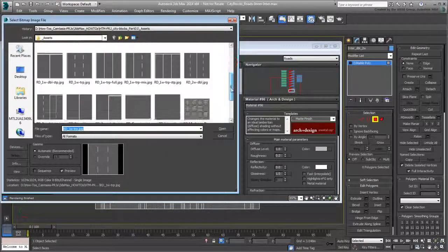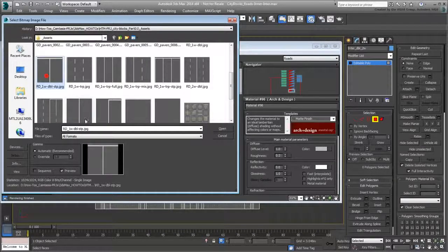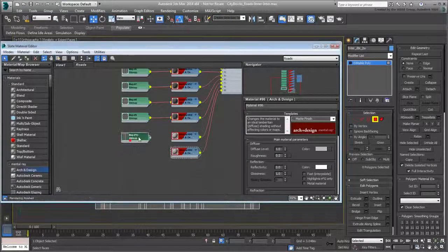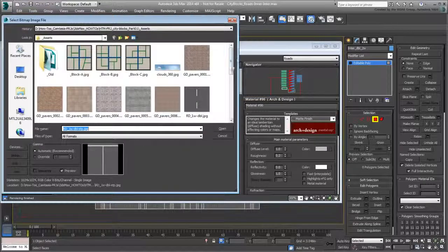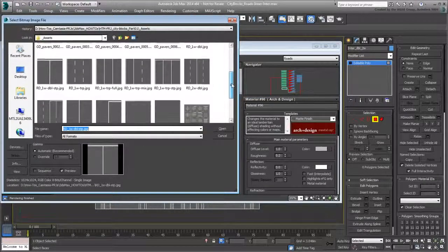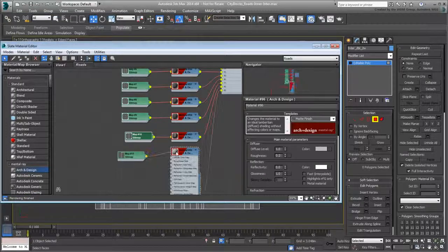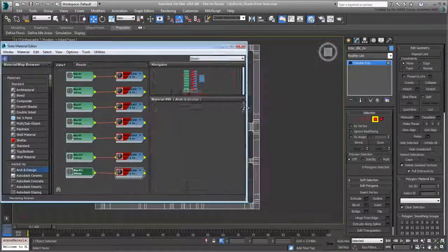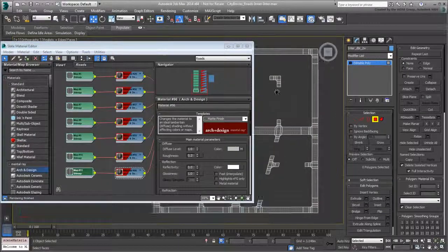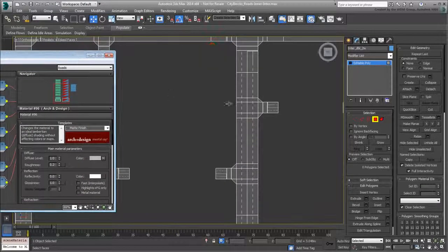The first one represents a stop line for a two-lane, one-way road. The second for a two-lane, two-way road. They are set as IDs number 8 and 9 respectively. Close the material editor when done, or move it out of the way.